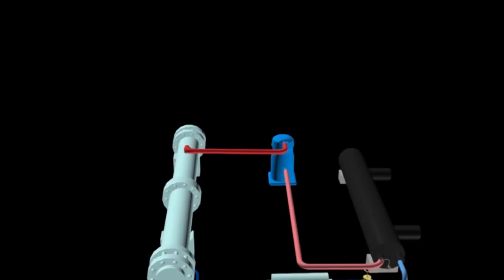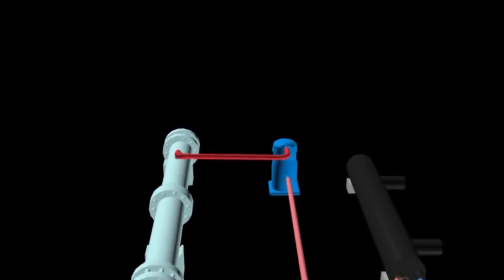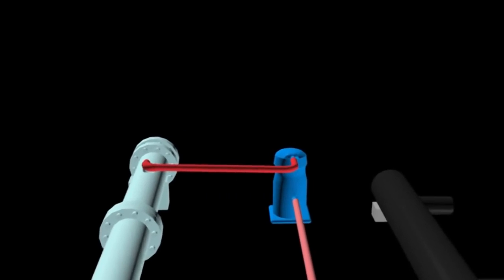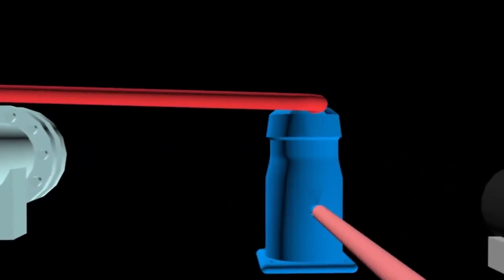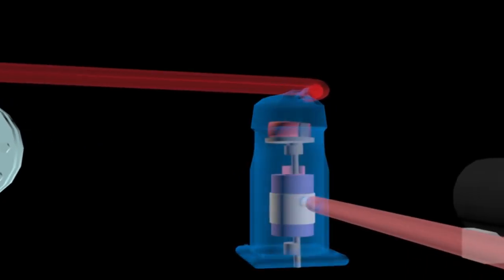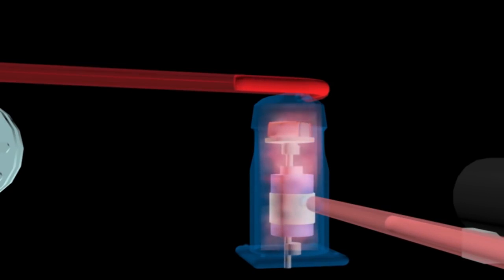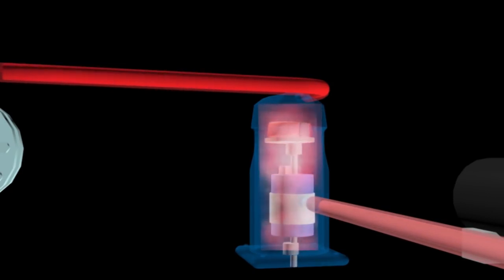Compressor. Compressor works to increase the pressure of the refrigerant. In addition, it also serves to increase the temperature of the refrigerant higher than the temperature of condenser water so that the heat transfer can occur in the condenser. The refrigerant enters the compressor as a low pressure gas and goes out as a high pressure gas.